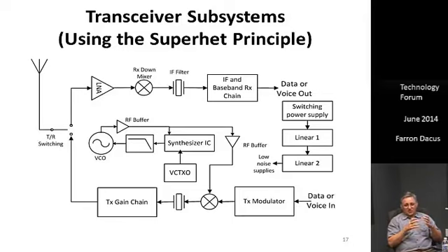Jitter on your oscillator, right, and that sets a lower limit on how low you can take the data rate or the bandwidth. So it looks great on the data sheet, but maybe doesn't get you the link budget you think you're getting. Well, they may be telling the truth because there's a way out of this trap.